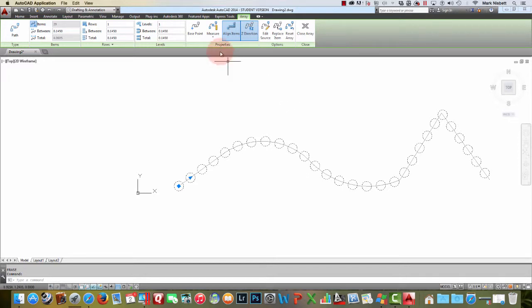Right now in here we're doing a measured array, so basically it's 1.450 along that. Each one of these is measured from the start, and each one is 0.145 between the centers, and whatever's left over is whatever's left over. If I change that number to say 0.25, we have 1/4 inch every spacing, and this is determined right here under measure.